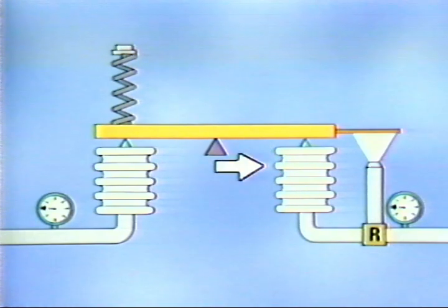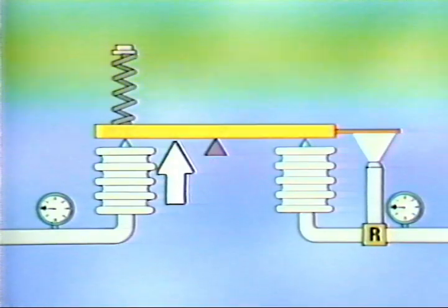Moving the pivot in the opposite direction produces the opposite effect. A larger amount of input change is needed to produce a full range change in output. So this would correspond to a wide proportional band setting.